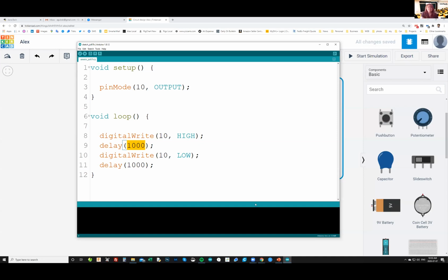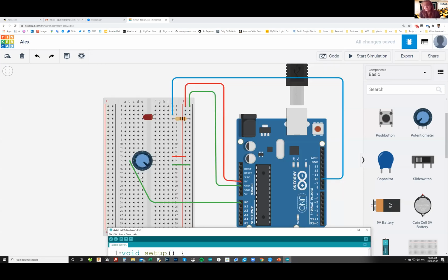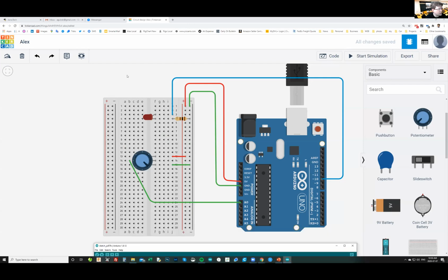The photoresistor isn't on the diagram yet, though. Guys, don't take it out yet. The photoresistor will be the second step. So for now, we only play with the potentiometer. Let's program this one first. Connect everything like it shows on the screen. I'm almost done. Don't worry, just one LED with the resistor.